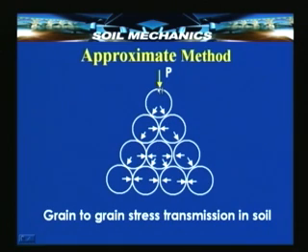This is a very useful thing, because the stresses must decay with depth, otherwise at infinite depth we will have infinite stress and the soil will not be in stable condition. This structure which I have shown here is a single grain structure. You must have already studied that there are other forms of soil structures, and therefore, there are other forms of distribution of stresses inside the soil. However, we shall make a gross assumption that all soil particles are spherical, uniform, identical, and the stress distribution is symmetrical. Let us see the next slide.